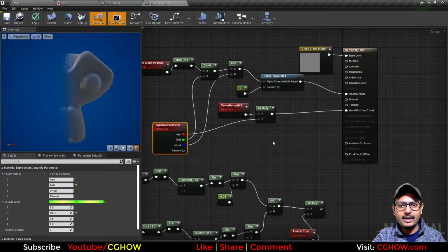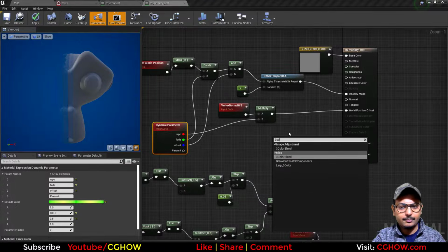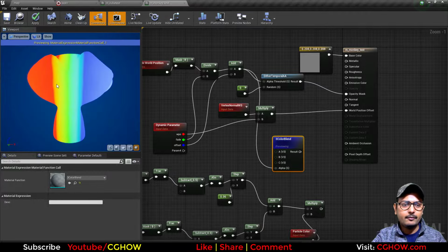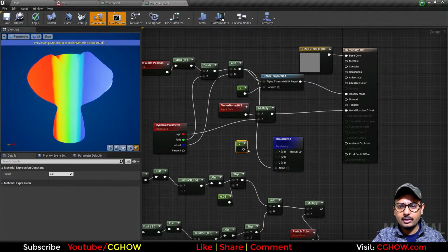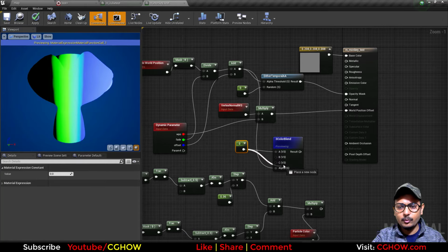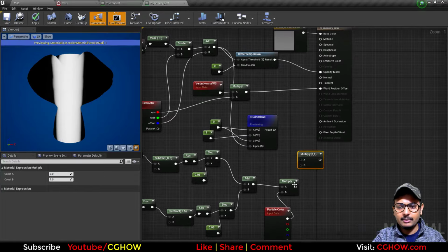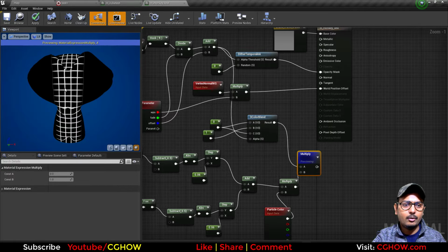So to get that edge you will take 3 color blend, connect this here, and now see we need the green color, so red and blue will be 0 and this green will be 1, that means white, and then you can multiply this with this, so your grid will only be visible here, and then you can connect it